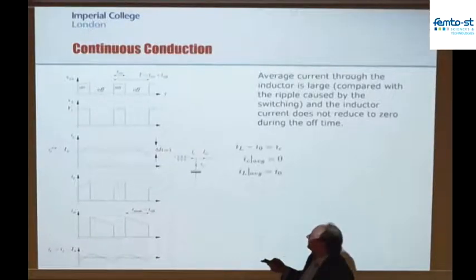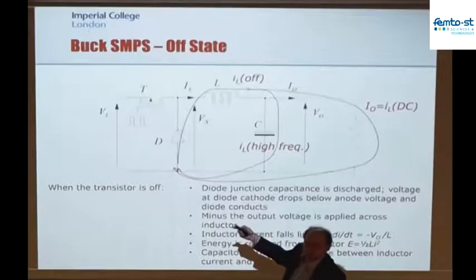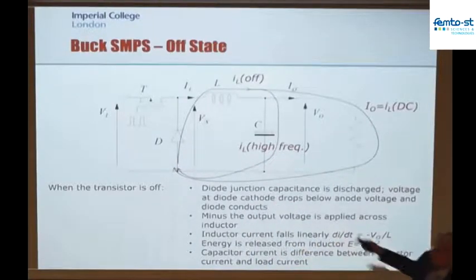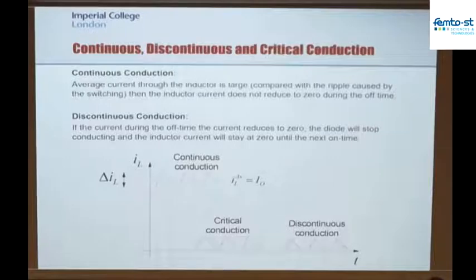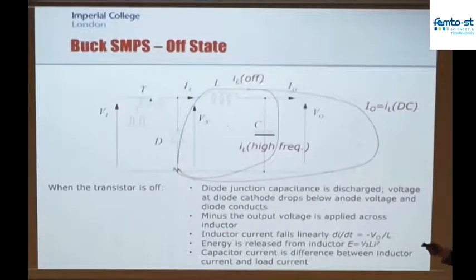So the voltage that we see at the output of the chopper, this bit here, is constantly going up and down. So we low-pass filter it so that we get the average value and we get a nice, smooth output voltage. Part of this is going to be designing this properly. If we don't design this low-pass filter properly, we won't get a smooth output voltage.